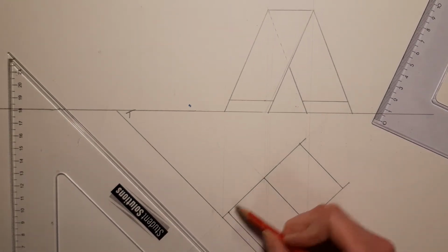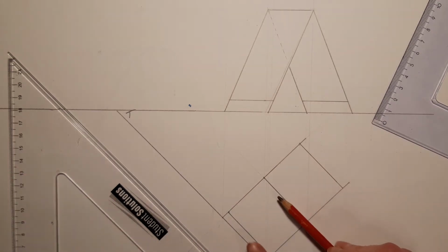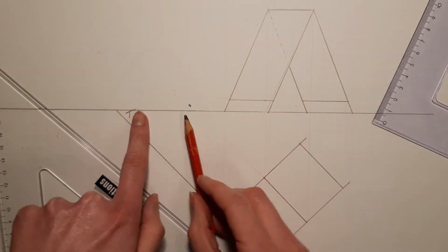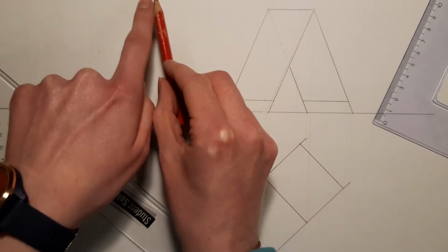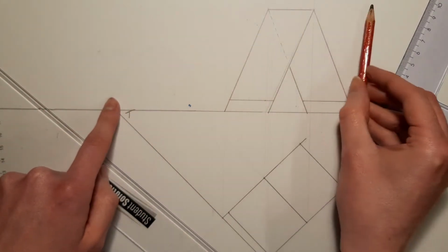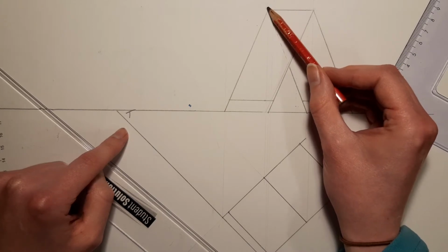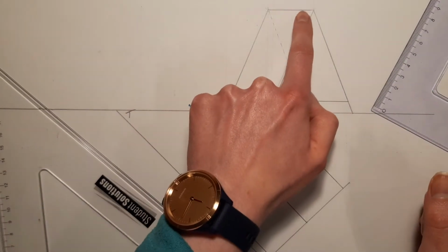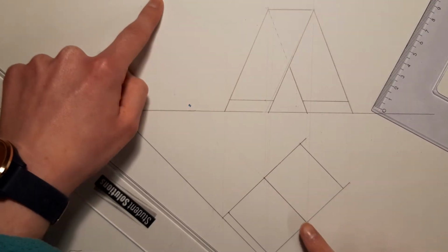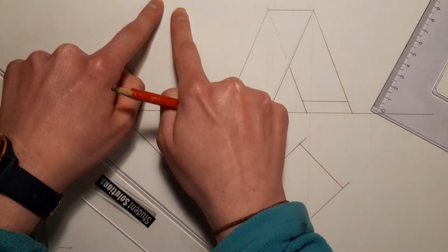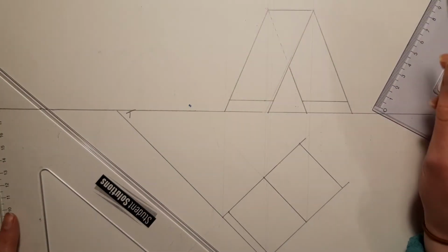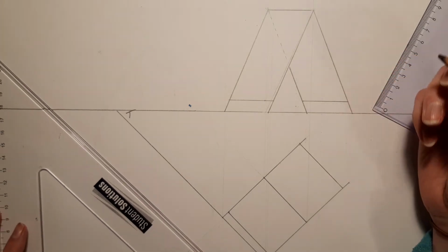If I want to find any of these points in elevation, usually what you do is you bring them parallel, up vertical until it touches on your VT, and across in order to find its actual position. But now that we have its position, I can work back in reverse. I can bring this across, bring this up parallel and see where it intersects, because that then will have to be a point on the vertical trace. So we've done this a few times.